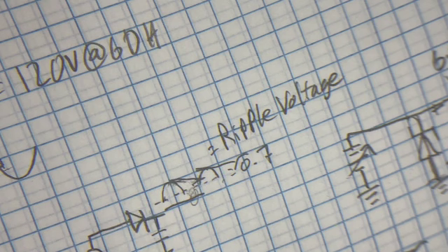Well, remember, every voltage source has its own internal impedance. So you put a resistance across the battery, you're creating a voltage divider with that internal impedance. Voltage divider means that that loss in voltage is dissipating across the internal impedance of the battery.